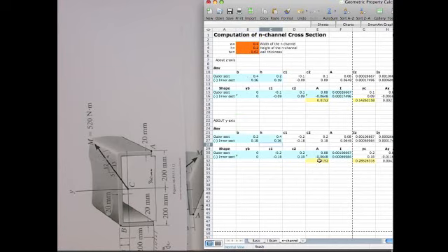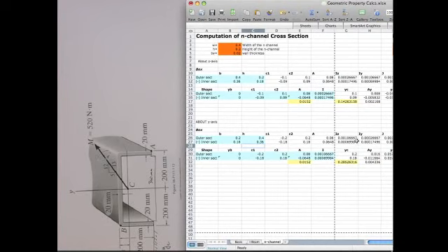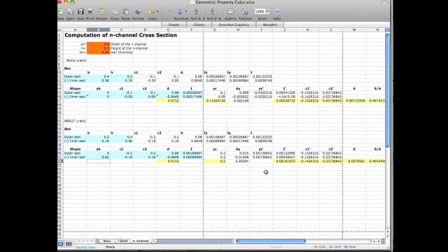Now, this is using the IZs instead of the IY. I'm sorry, it's using what was the IYs up here, right? You can see this comes to here, and these flip. So this is now doing the bending about the y-axis, this orientation. I have to shift the base point of the intersection. The base point of the intersection is now no longer at 0. It's actually up the 20 millimeters, the flange thickness, right? So now it shifted that up, and now we should have the calculation correct here. So this gives you about the y-axis.